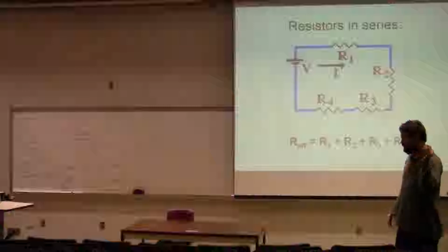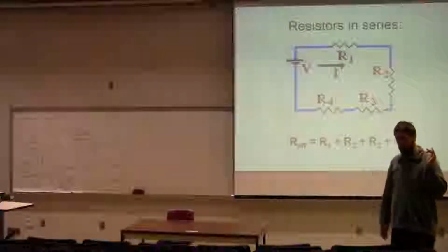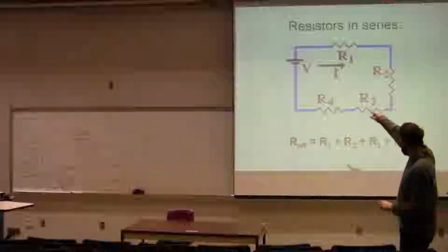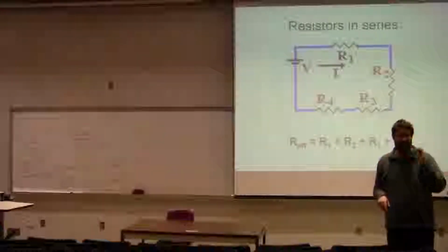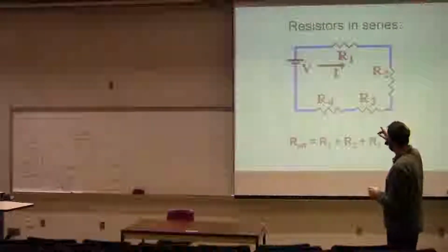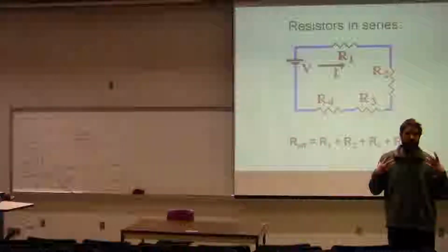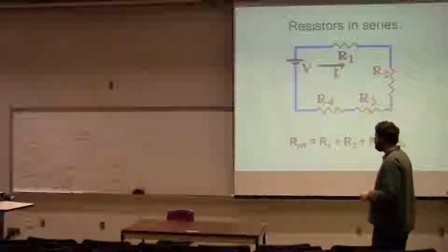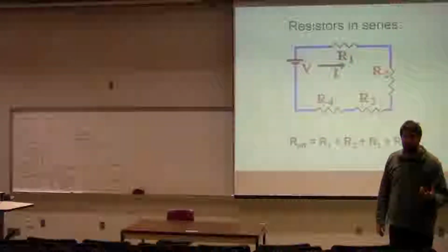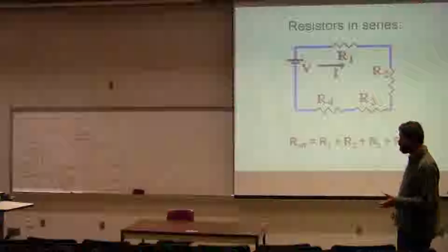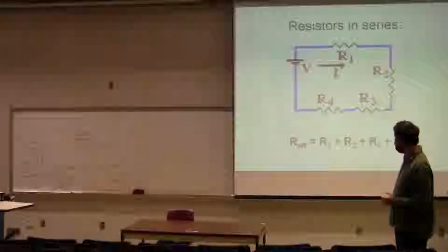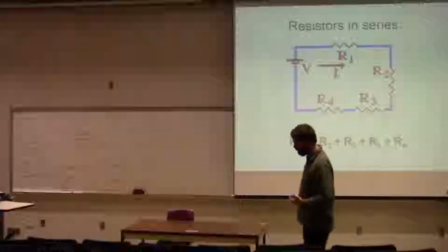Resistors don't collect energy. Energy passes through them. So the rate the energy passes into the resistor has to be the same as the rate it passes out of the resistor. It can't keep the energy. And so that current all the way across the circuit has to be the same. Because everywhere, energy in and energy out have to be the same. So R1, R2, R3, R4, and V all have the same current. So that means that if I take the effective resistance of the circuit times the effective current for the circuit, that equals the voltage of the circuit, which is going to be, in this case, equal to the voltage of the battery.